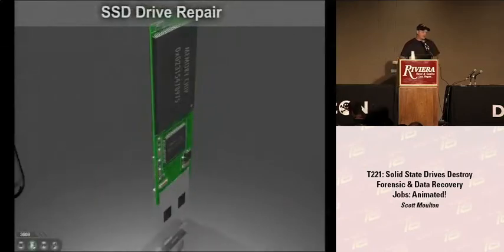Physically, it's kind of hard because some of the legs are obviously pretty small from that standpoint. There's not a lot you can do with them. It's a lot of work, and you usually have to have something like a chip quik that blows hot air on a chip to remove it. But the hardest part is obviously finding an exact duplicate, manufactured exactly the same way, with the exact same chip specifications, the whole thing, a donor to take the chips off of and put them onto, so you can repair a broken one of these memory sticks or some other thing.